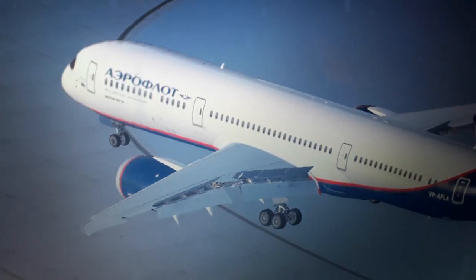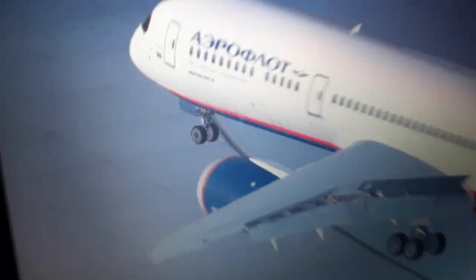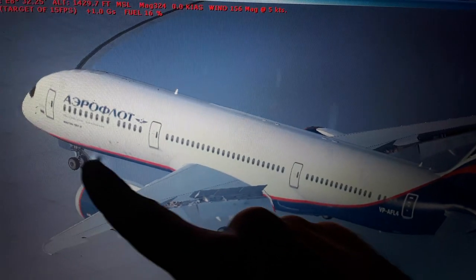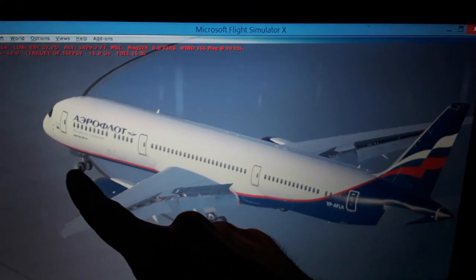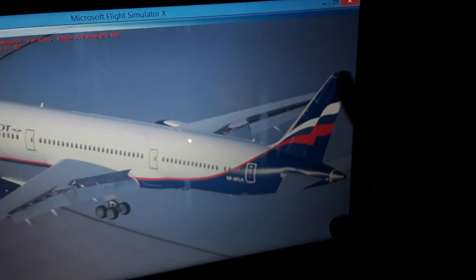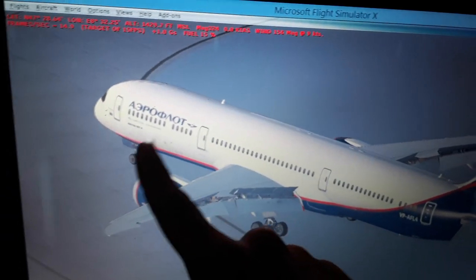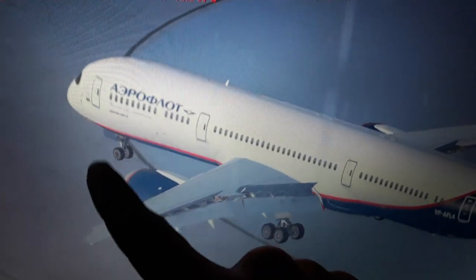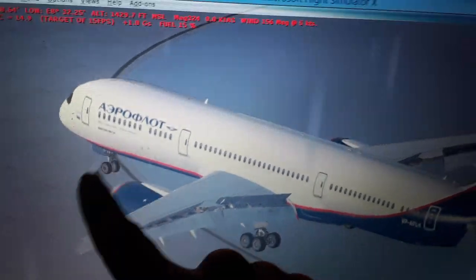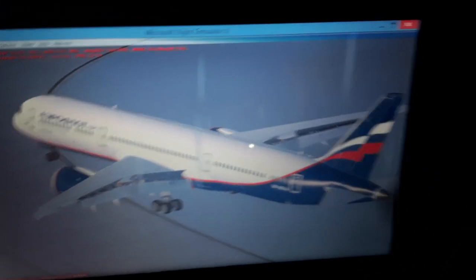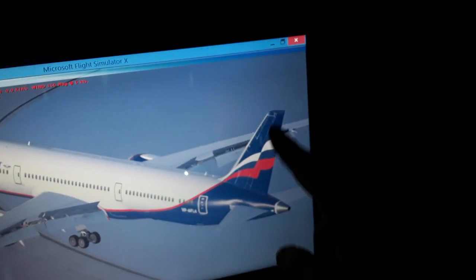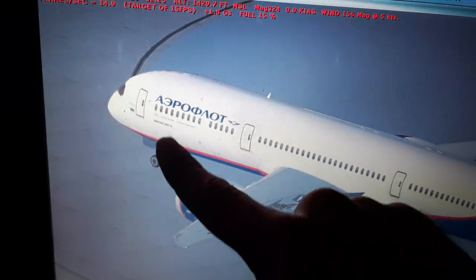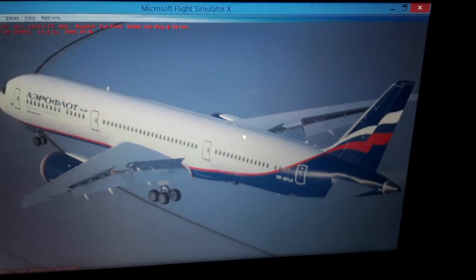So we have the nose wheel steering here. The nose wheel can turn left and right like 76 degrees using the rudder pedal. So the tiller on the ground from 0 knots airspeed to like 45 knots, we have the rudder coming in, aerodynamically effective. So the left and right nose wheel deflection decreases to like 7.6 degrees from 76. Then as we accelerate to like 80 knots, we have the rudder only become effective like 144 kilometers an hour. The nose wheel steering is locked to 0 deflection, it decreases to 0.